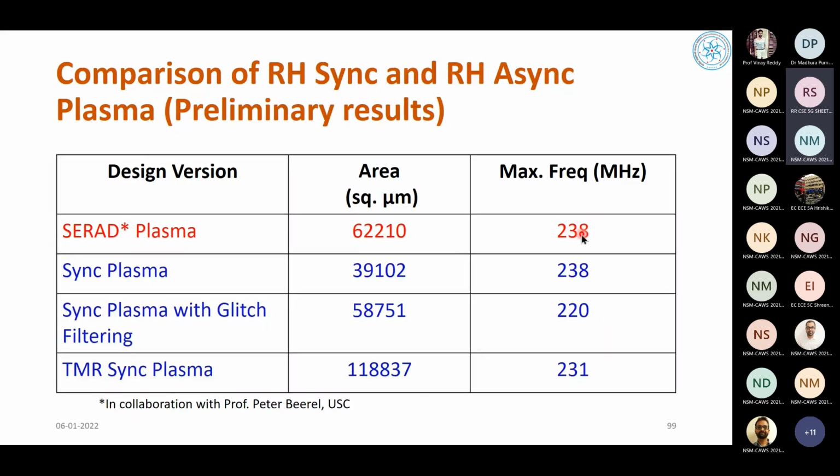We have basically used many tools in this work. A part of the circuit is implemented in Spice, let's say, and a part of it is implemented in Verilog. For getting these numbers, we have done the worst case analysis. We have taken the stage which is the slowest, and taken the worst case delay from there. Then we have taken the Spice netlist based worst case delay for the controller, and we've added them together. That is what gives us this frequency. Is it? Yes, ma'am. Okay.